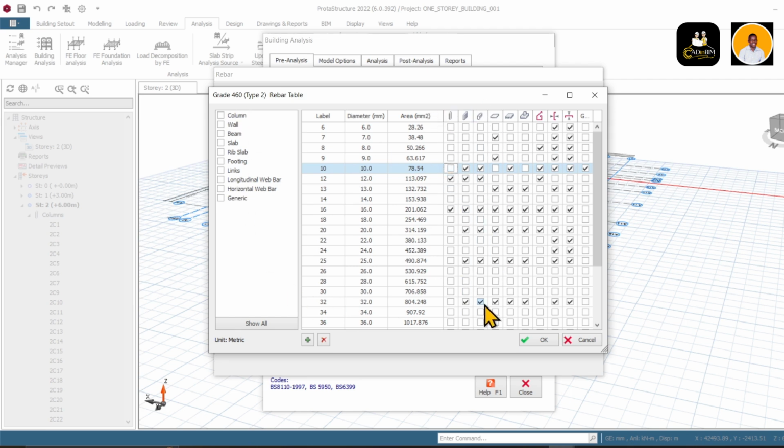Then when you come to beams, we'll be having maybe longer beams and we may require up to the 20, the 16, the 12, but not the 10. So uncheck the 10. Once we go to slab, we want our slab to be detailed with the 10, both the top bars and the bottom rebars. We don't have the 7 in the local market, so we just want the 10. So ensure that the 10 is what's checked here for the slabs.